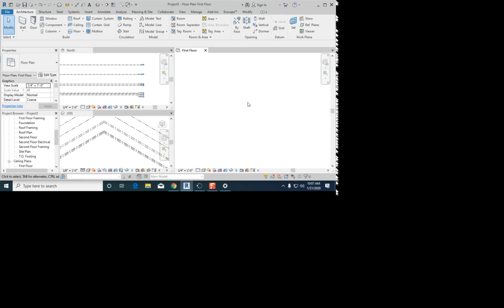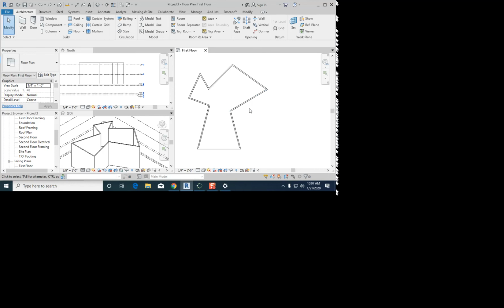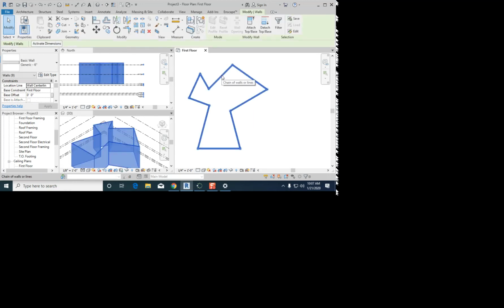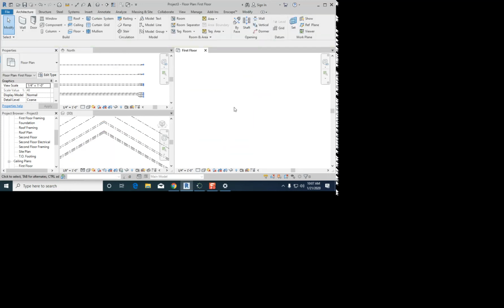Carol? Or if we're still in WA because we haven't done escape. Oh, yes, you have to do escape twice to get out of there. Sorry, good one. Okay, so if you're still drawing walls, yep, hit escape twice to get out of there. And then again, hover, tab, and then click, and then delete to get rid of those. So hopefully we are all starting with a clean slate now. Okay. Good.